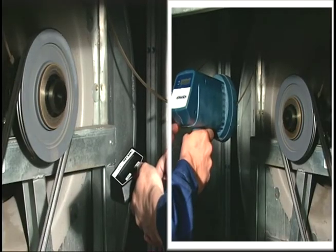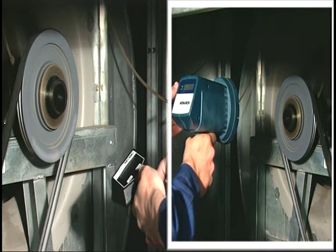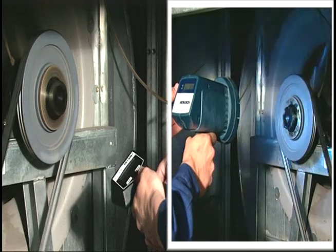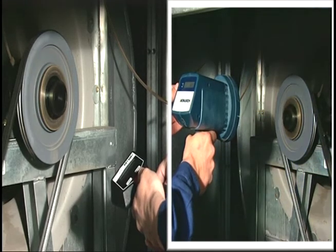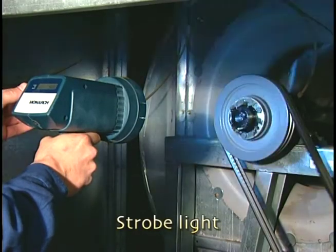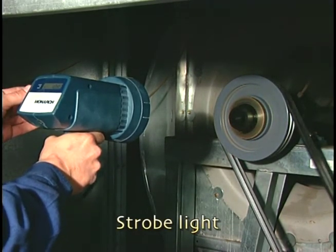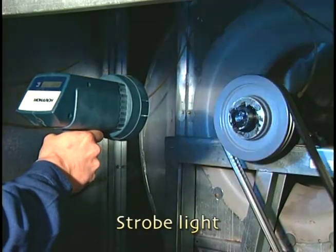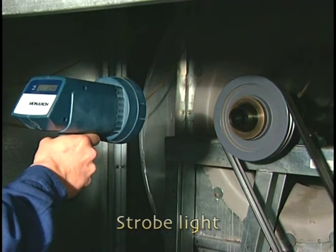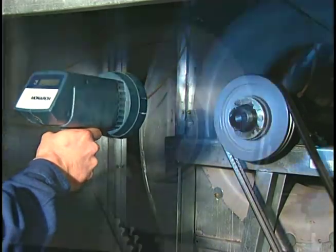When the shaft is not accessible, or for other reasons, non-contact tachometers, such as strobe lights and phototachometers, can be used to measure rotational speeds. A strobe light measures RPM by flashing an electronically controlled light at the rotating object. When the electronic flash is synchronized with the speed of the rotating object, the object will appear to stand still.